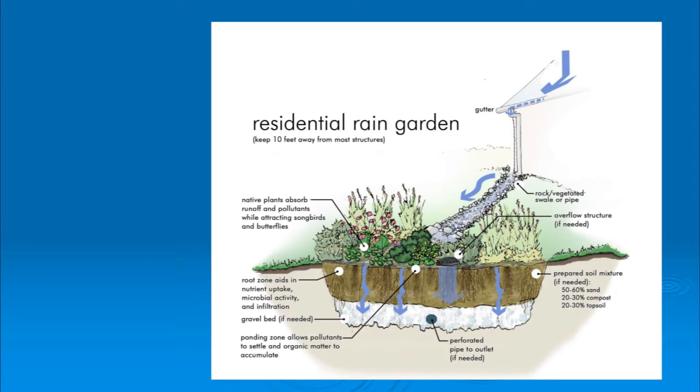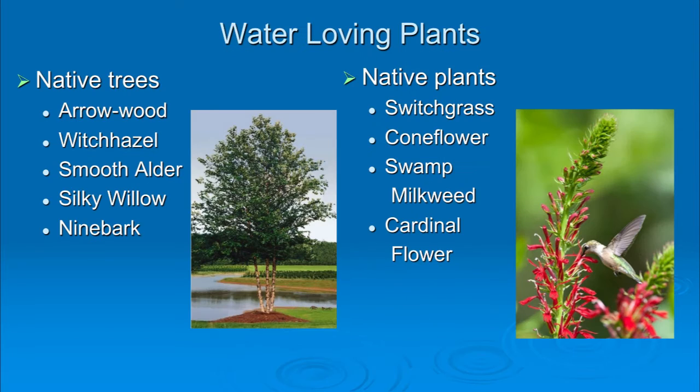And then I always want that to be at least 4 or 6 inches below your current ground level around your garden. So it does look like a depression when it's done. So again, it will hold that water temporarily, up to 24 hours, and give that water an opportunity to move down through the soil, hit the stone, and then easily access the groundwater. So again, I'll bring that up at the end if anybody has any questions.